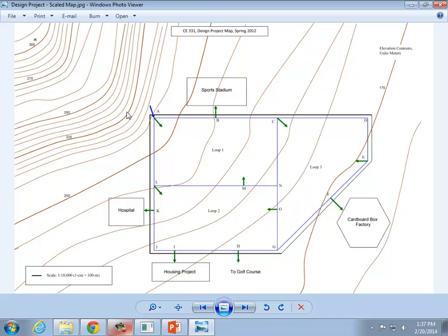An important thing that I mention is that when you get into the design phase, there's two conditions that you need to know the flow rate estimates for. And one of them is the maximum hourly flow. And by that, what it means is for the peak hour of the peak day, so the hottest day of the year at 8 p.m., what is the flow rate that's being consumed in terms of liters per second at the peak hour of the peak day?